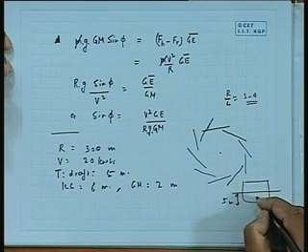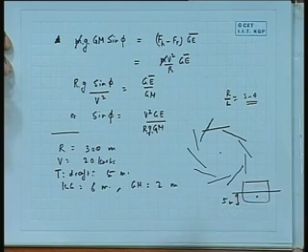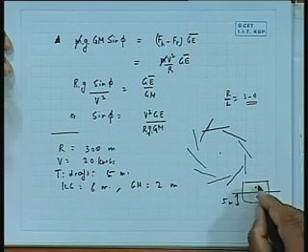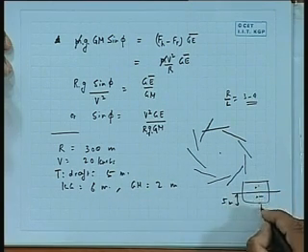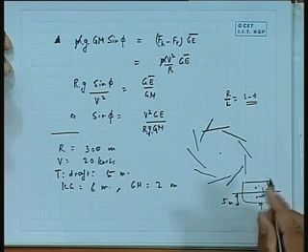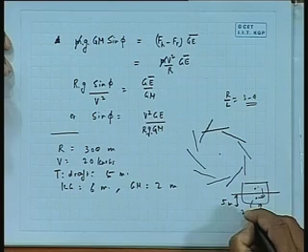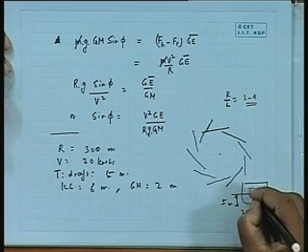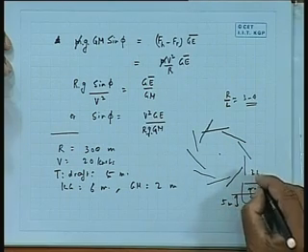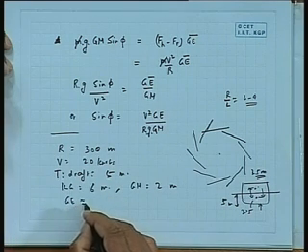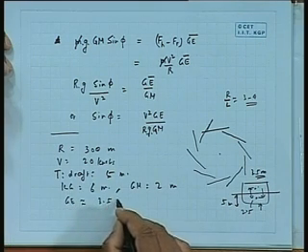So you can take the center of action to be halfway through, and KG is 6 meter, that is, K to G is 6 meter. So I can take this to be 2.5 meter, so that this distance becomes 3.5 meter. So you see what happened, GE becomes approximately 3.5 meter.